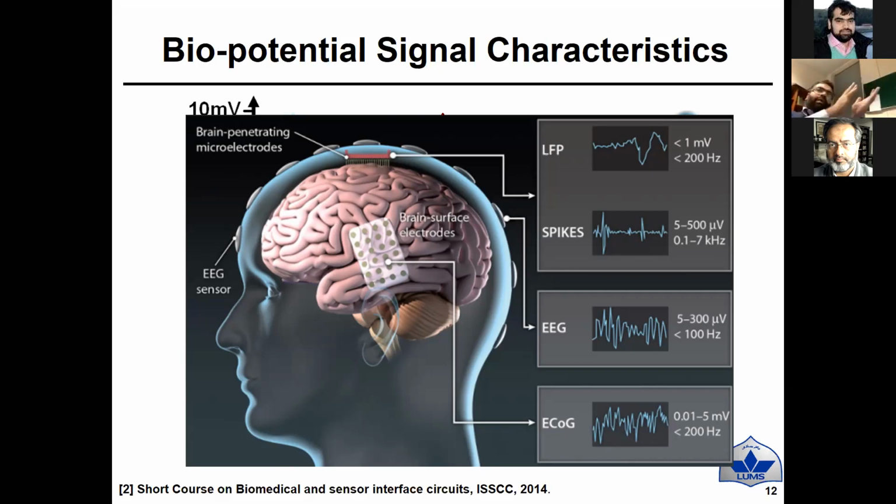So again, जब आपके पास signal आता है, उस signal की आगे electronics आपको, that's the main daunting task. ये जो मैं amplitude show कर रहा हूँ, you can say they are very much small amplitudes. They are overall overwhelmed with noise, and because of very much low frequency, there are a lot of issues which you need to deal at the front end side.